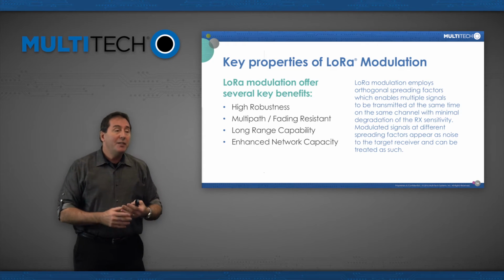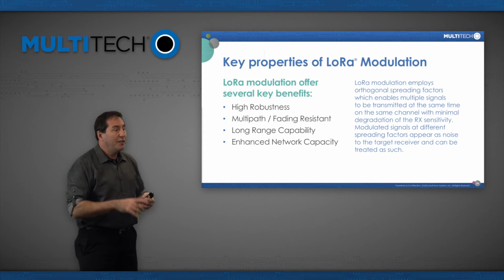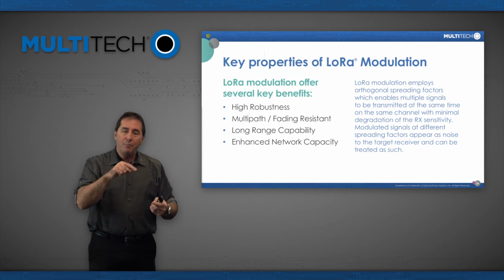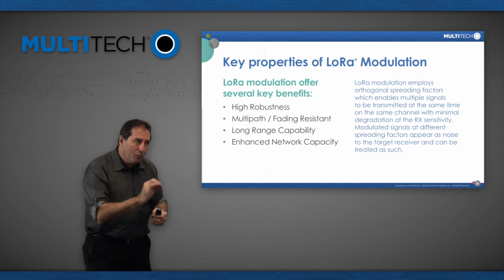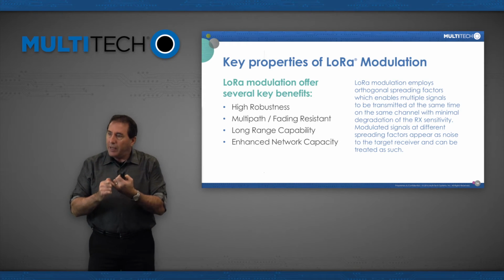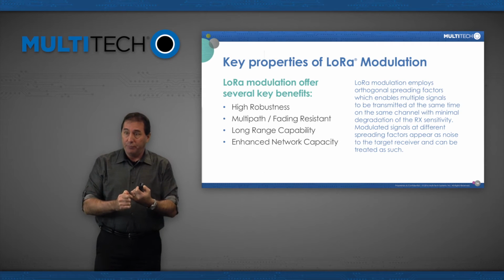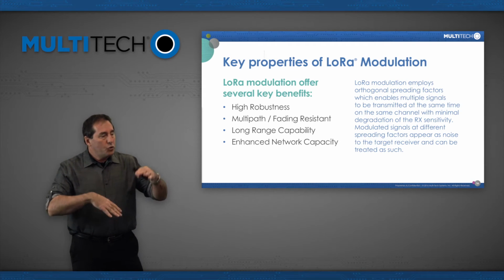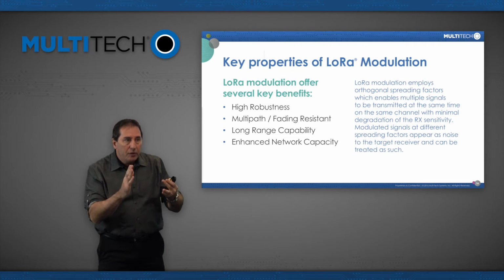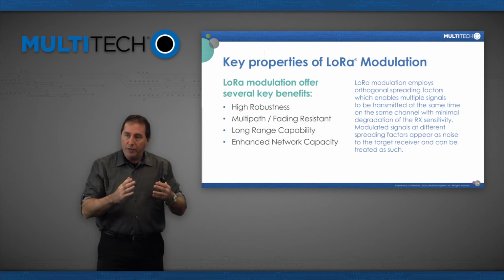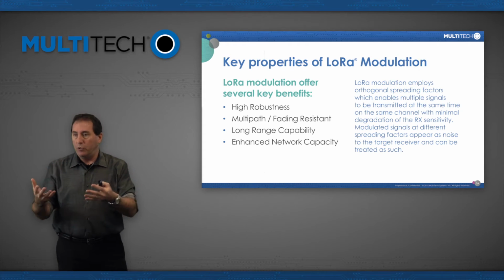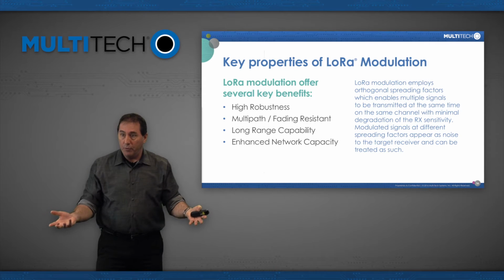And the answer is, today, yes, that's kind of true. Except there are other factors that make that argument not quite right. One is that LoRaWAN has an adaptive data rate function, so it controls endpoints and the channel they use and how they talk, to allow more people to talk than you would normally have in a regular LoRa network.